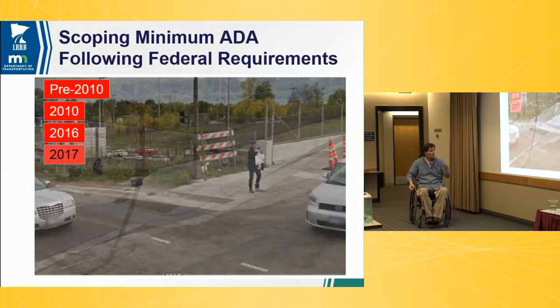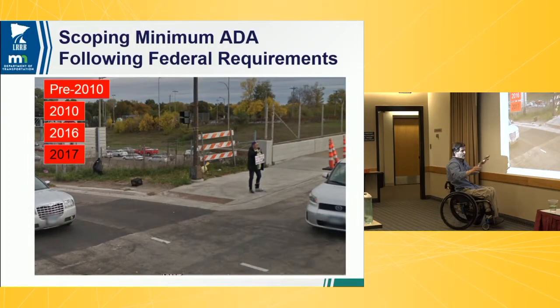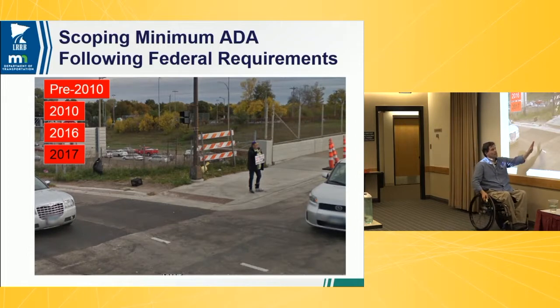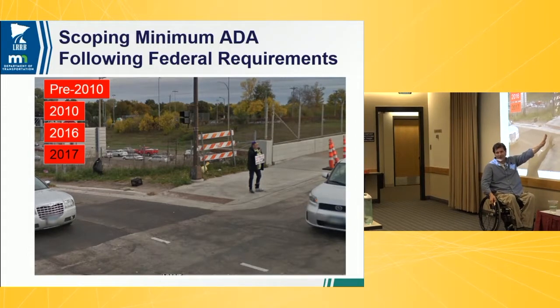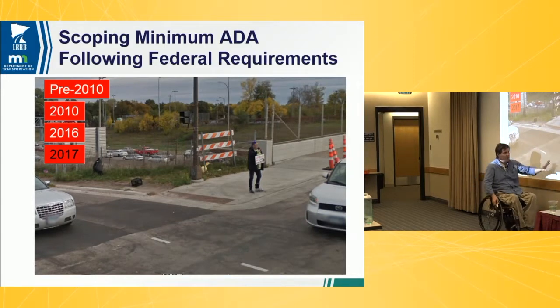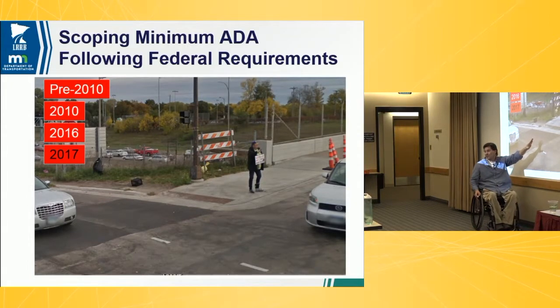In 2017, the county was going to do an overlay project. They were going to come here and do curb ramps early, and they wanted to remove this failing crosswalk. So they did that. But we said, yeah, you can't really fix this curb ramp unless you start going down the road here. They were going to pave this whole intersection, and again, we told them not to improve the ramps because they really couldn't have with that scope of project, because we were coming in here in 2019 with an overlay, and that's where we're going to do some of this raise that we're talking about, get a super through this area.